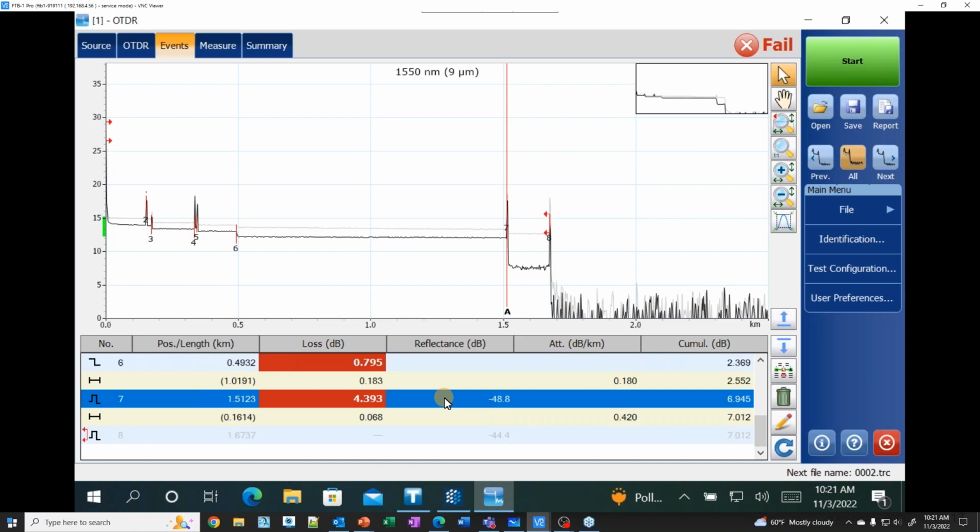There's a lot of pinches in existing fiber out there, in existing raceways, existing splice trays, that haven't been a huge issue because you're running an old FLM 2400 on it that's using 1310 nanometers. You know, when the world ends, it's going to be cockroaches and the FLM 2400 running at 1310. The things just work because they're low bandwidth, short wavelength equipment. And so now we need to troubleshoot this. This is not a bad connection. This is not a bad splice. I'm not going to go out there, expose the case, and break a splice and redo it.